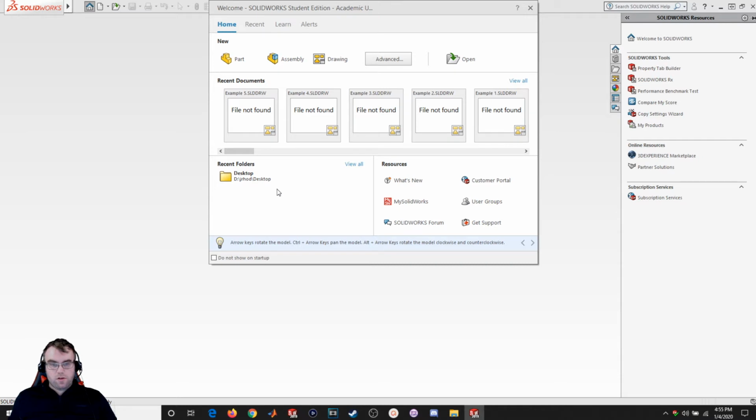Alright, so if this is your first time opening SolidWorks, it's probably going to ask you to declare what kind of unit system you're working in, whether it be ANSI or ISO. If you're part of my classes, go ahead and select ANSI as your units, because you're mostly going to be working within inches for most of the parts that we do.